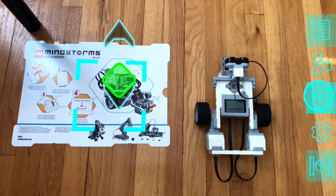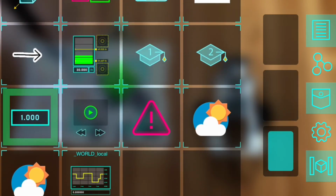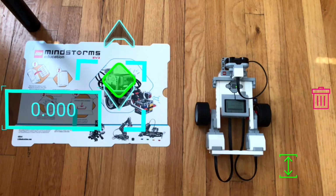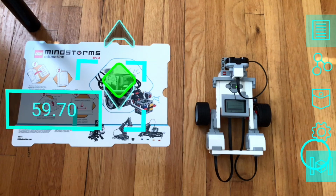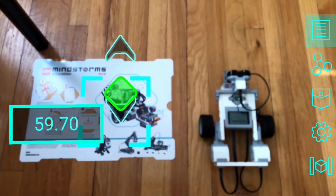We can go back into our pocket and we're going to grab a value tool. So this way we can see what the distance sensor is reading on the EV3. So again, we're going to resize the tool and move it in our space. We're going to connect it up to the ultra node. So this reads in from the ultrasonic sensor. And you can see it updates to around 60 centimeters. If we unfreeze the screen, you can see there's a box about 60 centimeters away from the EV3.